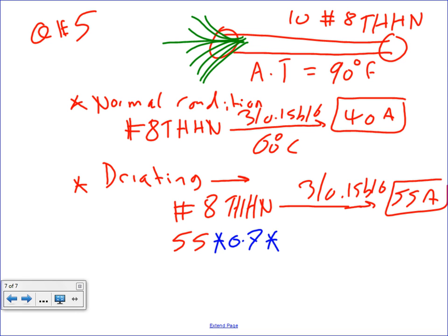For 90-degree temperature, Fahrenheit, don't forget it's Fahrenheit, your derating factor is 0.96, right, Chris? Right, Phil? For 90-degree ambient temperature, 87 to 95, I have 0.96. I'm sorry, the first one should be, I have 10 of them, so this should be 0.5, right? For 10, it's 0.5.